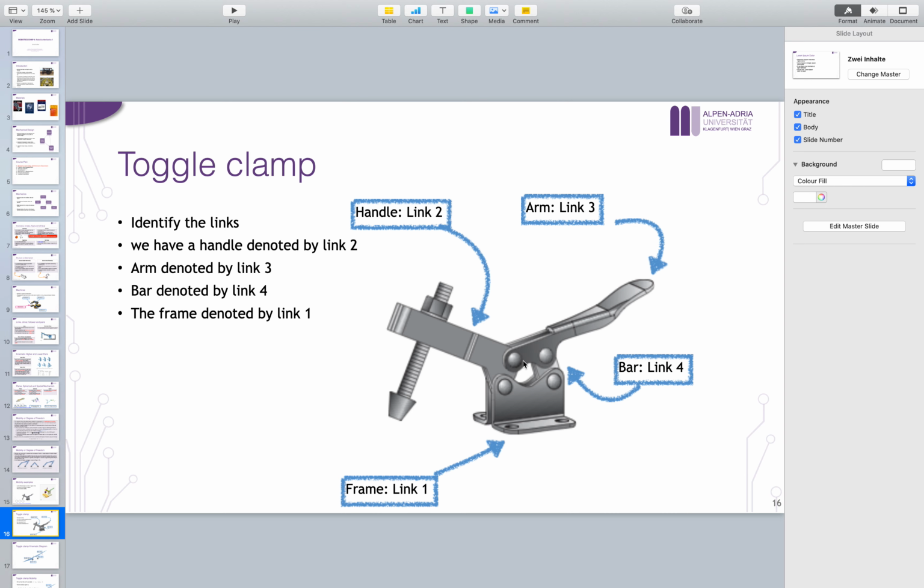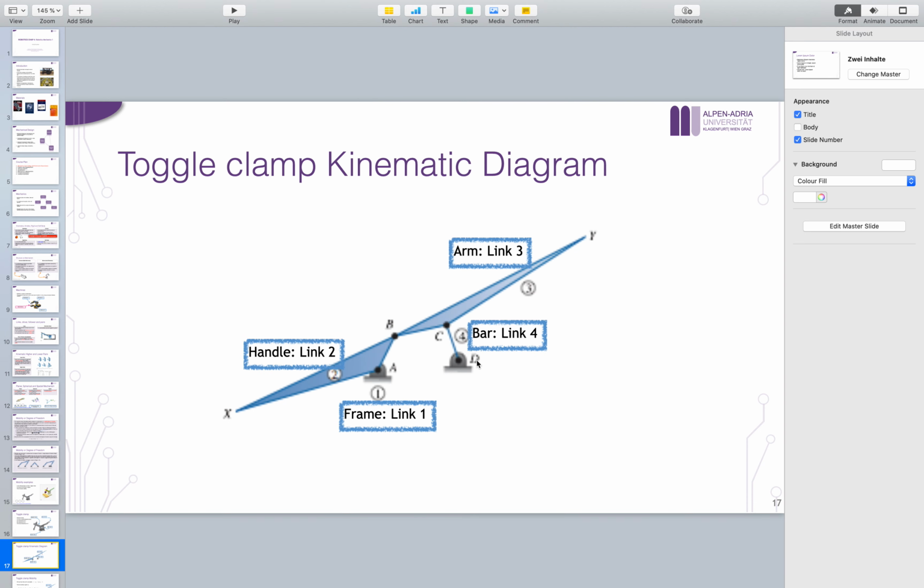A complex link has a complex shape and is connected by multiple parts of its body. A simple link, represented by a line, has two ends, and only those two ends are connected. The triangle has three ends, 1, 2, 3, and 2 of them are connected, and the third is not connected. This is a complex link.